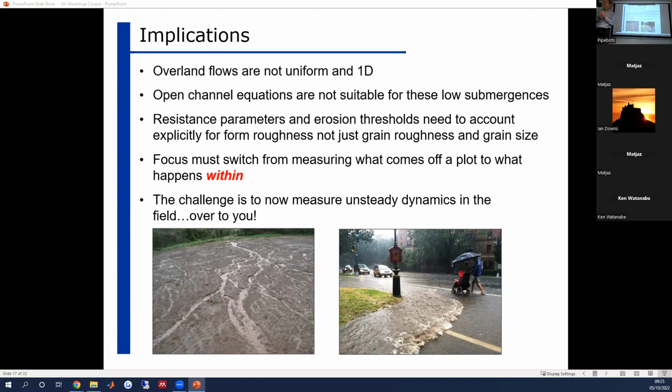And how do you measure the water depth? Yeah, so we did a laser scan of the water surface. And knowing the elevation of the eroded surface below, and knowing that's fixed, then we could calculate the depth. Okay. Yeah, that's right.